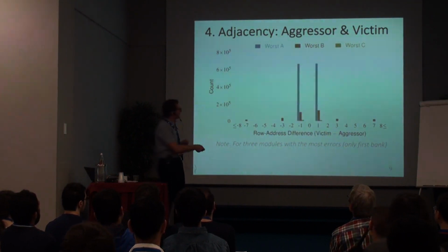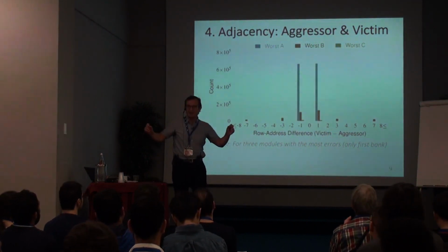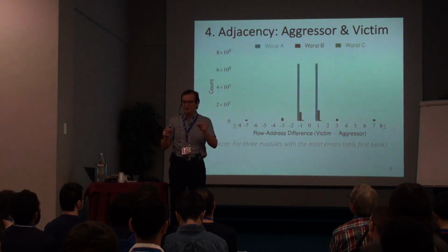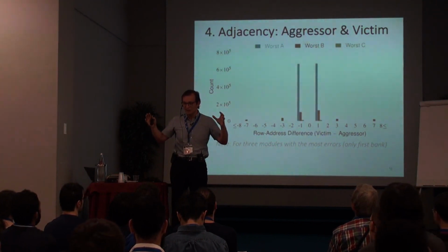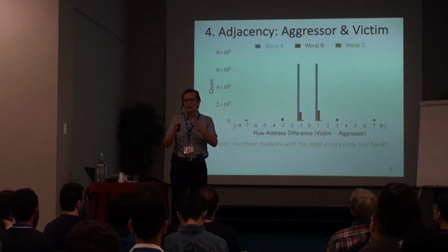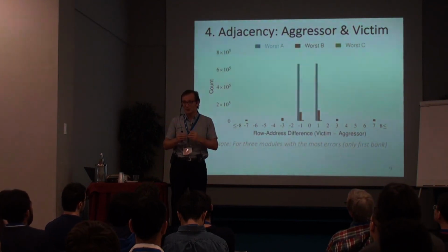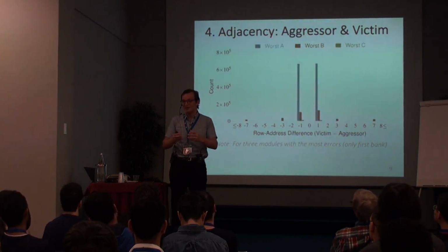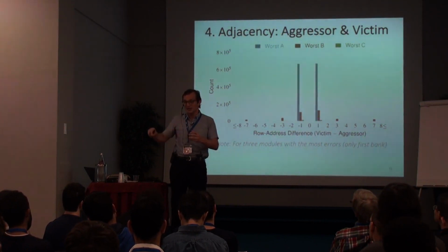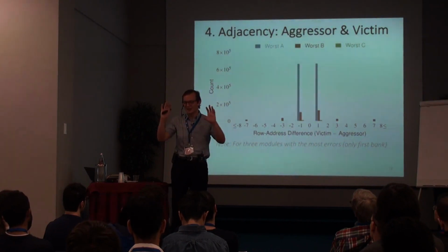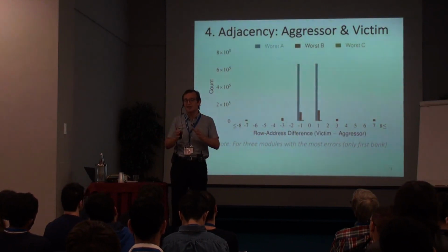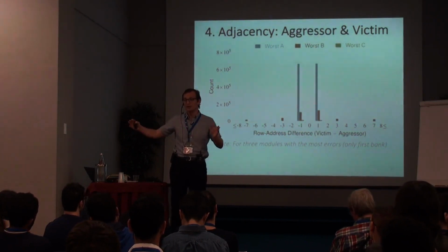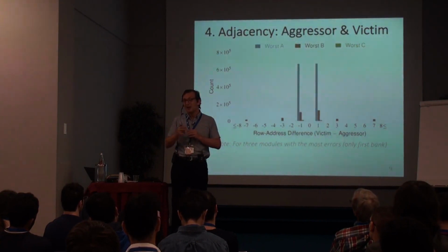It depends on what these are. I think if these things that are far away are because of remapped rows, which I believe, it might change with the size of memory, size of the chip, because as you increase the size of the chip, you're probably at a much lower technology node, which means that you probably have more errors that you've discovered, and your remappings may actually increase. So that might be one reason this might change, but I don't expect it to change really heavily, unless the manufacturers increase the number of rows that are used for remapping internally. There might be a case for that, actually.